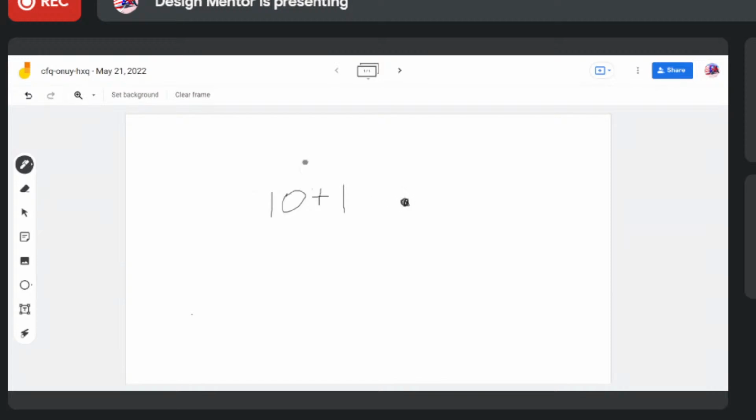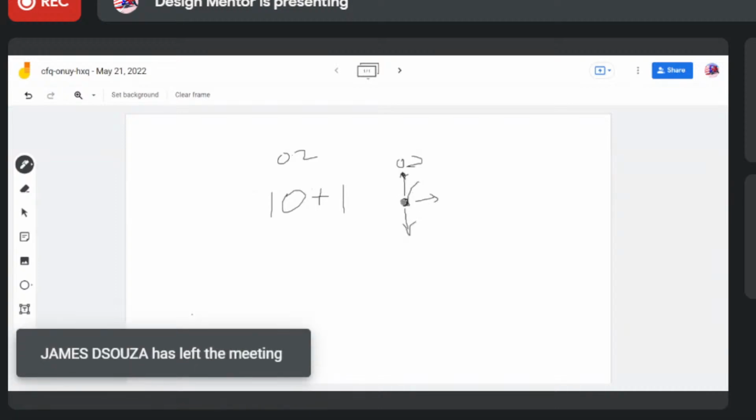First what used to happen, we used to have a square tolerancing system, where if the tolerance is 0.2, the hole can be 0.2 mm away in this direction, 0.2 here, 0.2 here, or 0.2 in whatever direction.